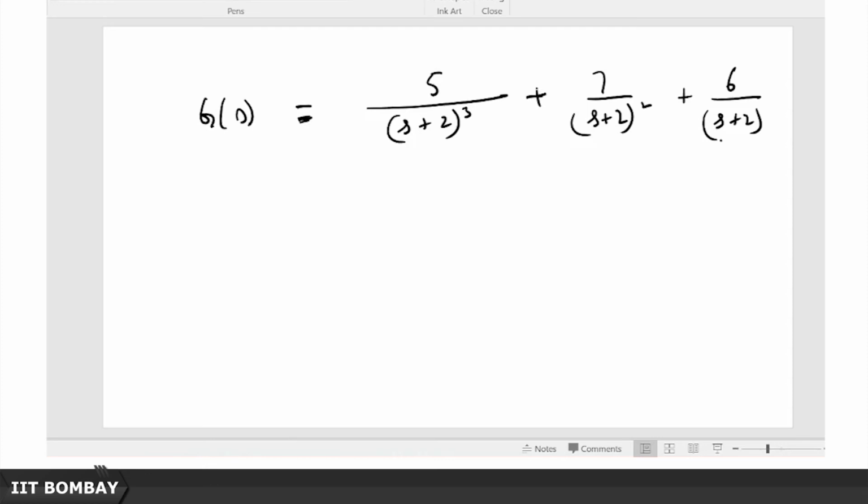Now clearly I can at most realize this block in the standard fashion, so let me go ahead and do that. But I also know that I have to realize a third degree transfer function, so I need 3 integrators, but maybe I cannot put them all in parallel now, so maybe I will have to put them in series somehow. Remember, this is only one part, which is concerned with the repeated poles.